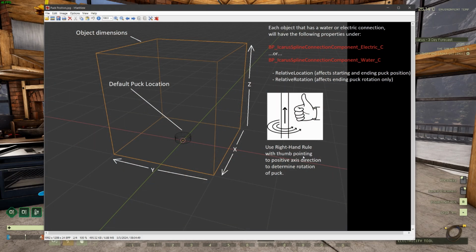When you're looking at where that is, it usually defaults to the very middle of your model, like in this location here. If you want to move it, and this is looking at the front of your model, the relative positions of movement are plus in the y direction this way, negative this way, and then positive x direction is going to be coming closer towards you, and negative is going to go towards the back. Z is going to go up, positive, and negative is going to go down.